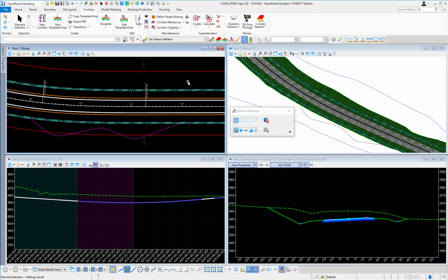In this video, we're going to take a look at point controls with OpenRoads Designer. A point control is used to override the normal location of one or more points or components in a cross-section. Examples of this could include lane or shoulder widening, staying within the right-of-way, maybe with an end condition, or maintaining a particular ditch profile. And your super elevation points are also controlled with point controls.